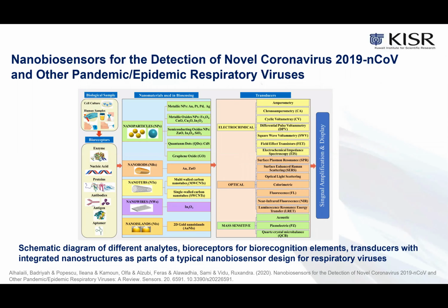The target molecule attaches to the bioreceptor to detect the biological molecule by a particular reaction, and then the transducer with integrated nanostructure will convert the detection into an electrical signal to be determined by the detector. Different nanobiosensors designed for respiratory viruses have been included, such as electrochemical, optical, and piezoelectric nanobiosensors.